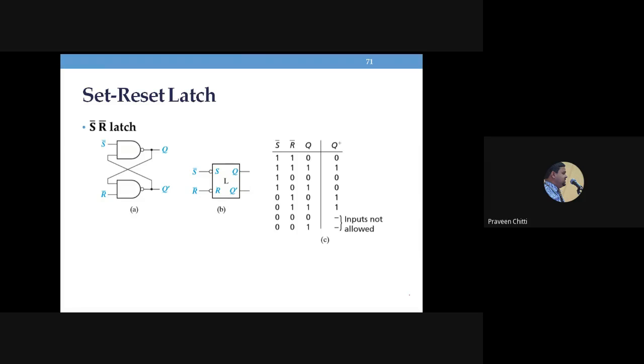We'll go ahead now. Quickly, I will explain SR latch using cross-coupled NAND gates. Again, I have used a similar structure to how we use cross-coupled NOR gates. Now we are using NAND gates. This is NAND gate 1, NAND gate 2. But instead of giving the inputs as R and S, I have shown the input here is S bar, and the input here is R bar. That means S will be complemented and given here. R also will be complemented and given here.